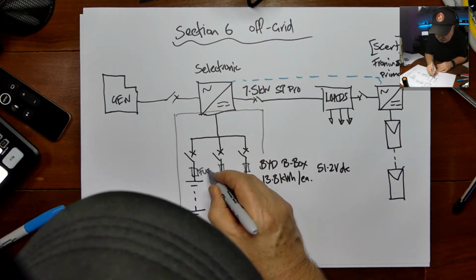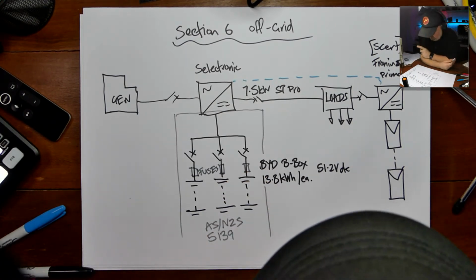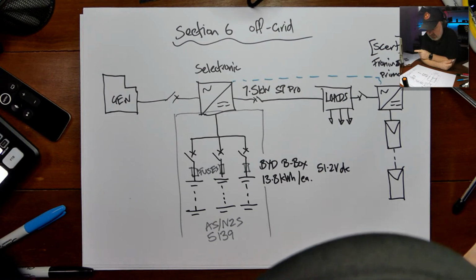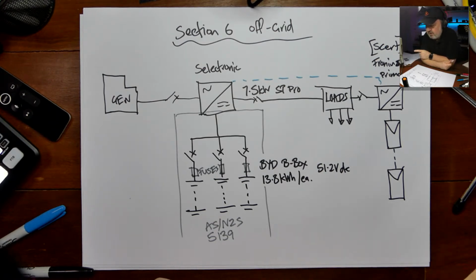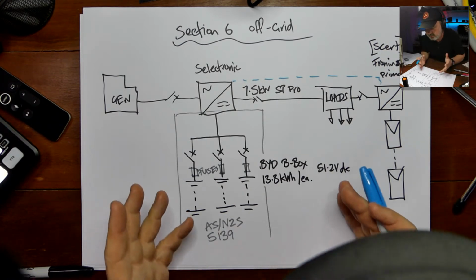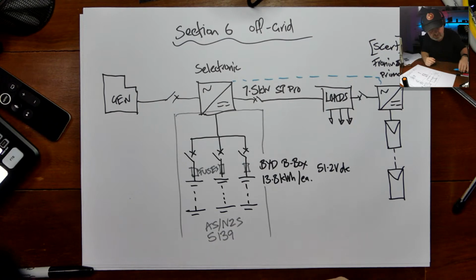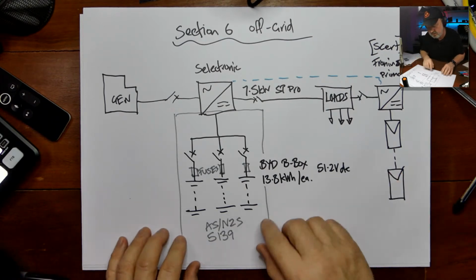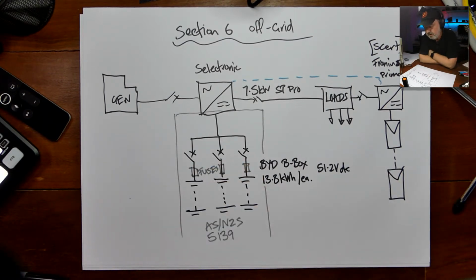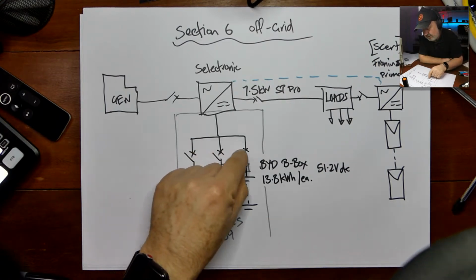So there's our fuses here. So we meet the first requirement that I wanted to look at in terms of 5139, which is you must have overcurrent protection in each string of a battery system. But there is no isolation device in that box. There's no switch to turn off, or air gap switch that can interrupt the current. There's a semiconductor switch for turning off the BMS, but there's no internal readily accessible switch. So I've had to add those externally.